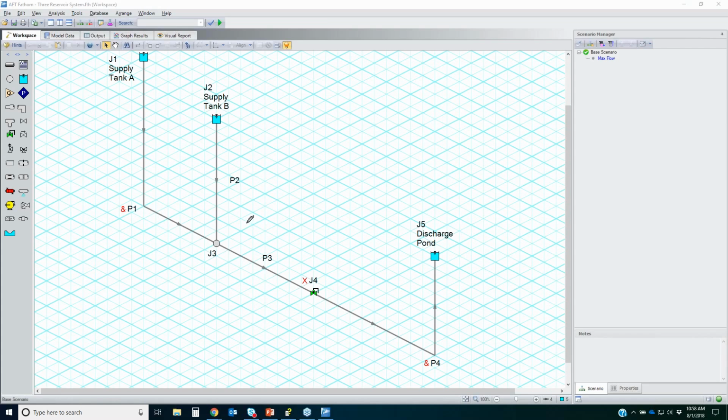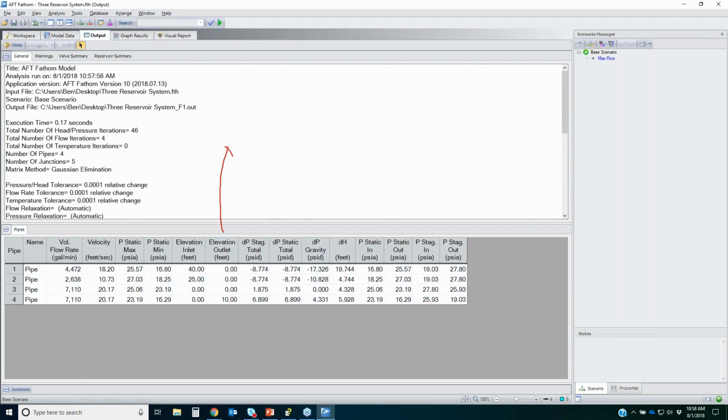is that if you had reverse flow in that pipe, you would see a negative flow rate in your results. So the negative flow rate would be a negative value. And that's not really a problem. It just means that your flow is going backwards. However, if you have fittings in that pipe, sometimes the losses through your fittings can depend on flow direction, so your fitting losses may not be as accurate. It shouldn't have a huge effect, but it might cause slight differences.